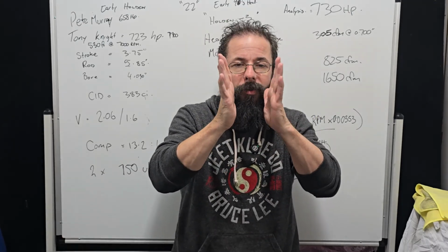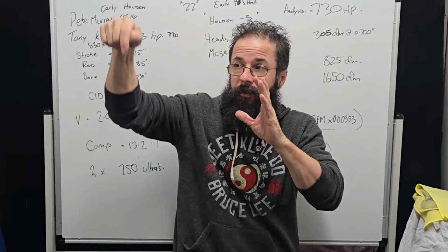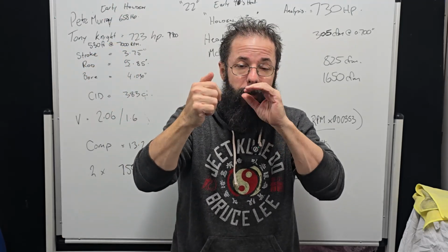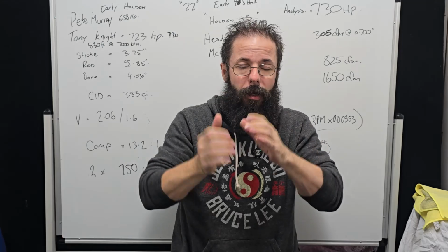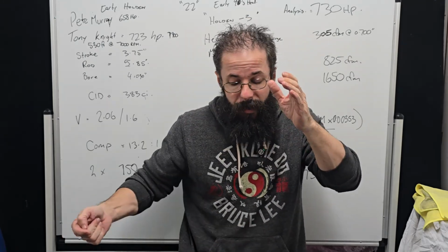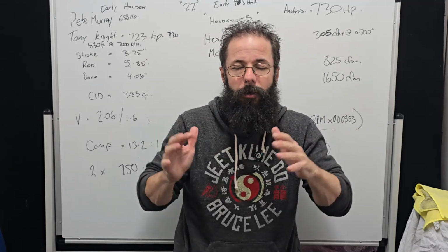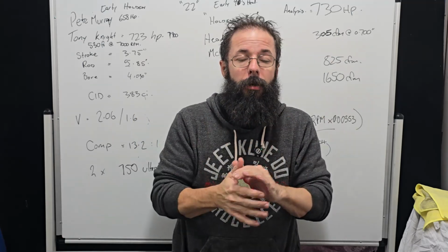Now, the whole point of a booster is to create a venturi, a low pressure to help atmospheric pressure push the fuel up into the emulsion tube, into the body of the booster, and that helps atomize fuel. But if we have this positive wave coming back up, we lose signal and we can create all sorts of problems, stutters and all sorts of problems.